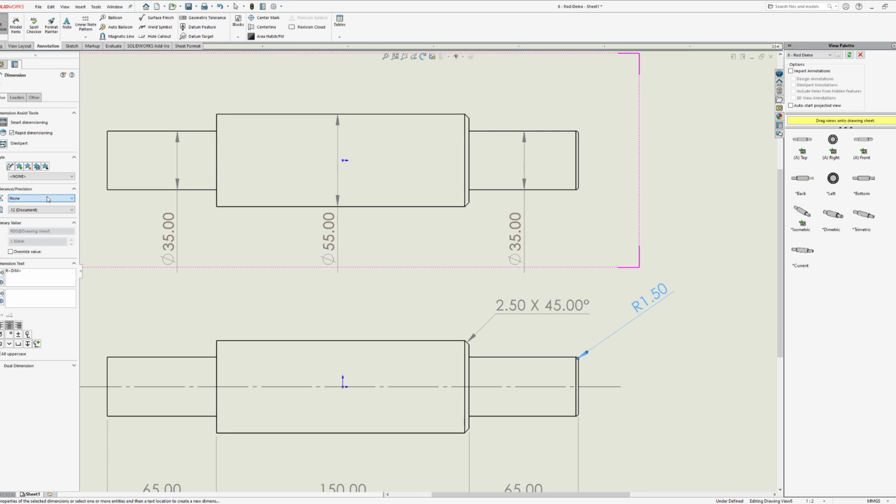So tolerance is just going to go into the details of maybe how many digits you want after your number. Most of these default to the hundredths place. However, if you have very specific measurements, I can change it to be even more than that. You just need to click the drop down menu and it will go to, what is that, 8 values after the decimal place, which, if you need that much tolerance, you got it, but that is a hefty amount right there.